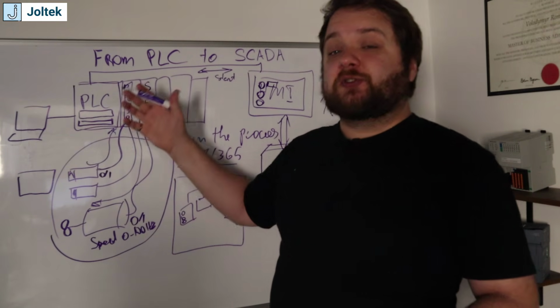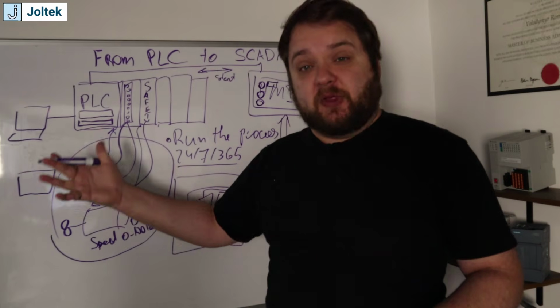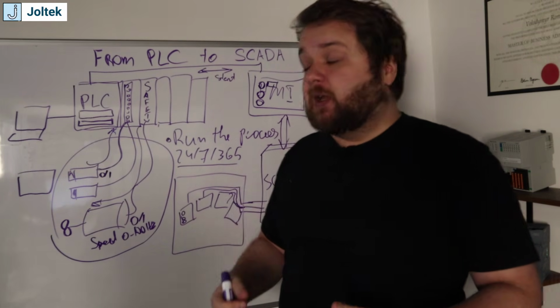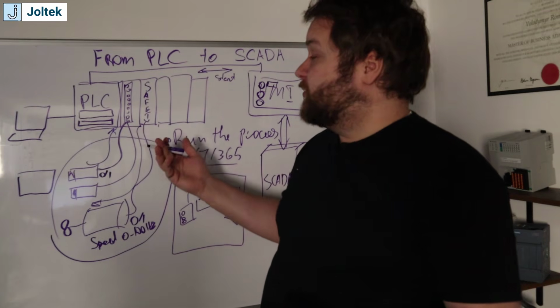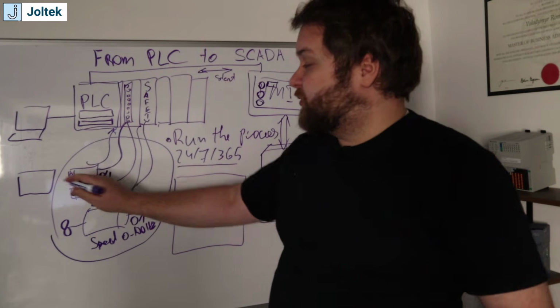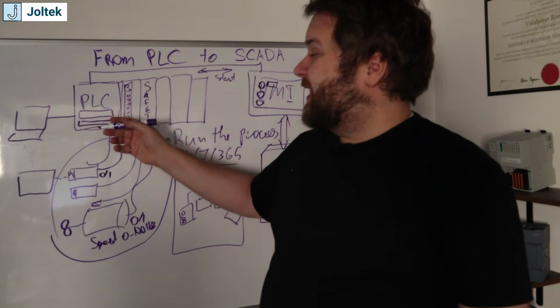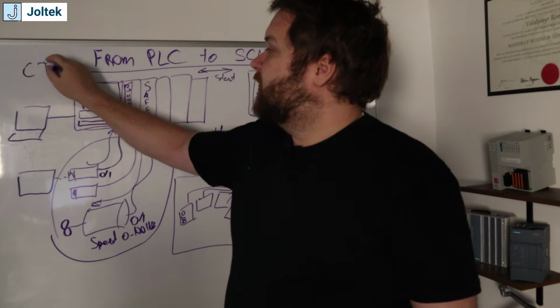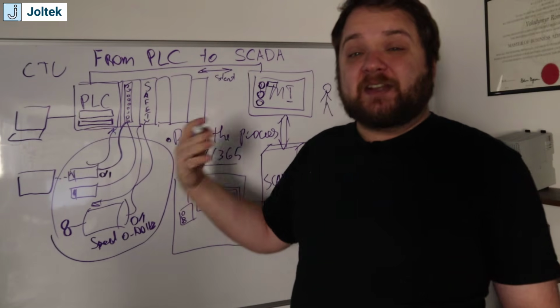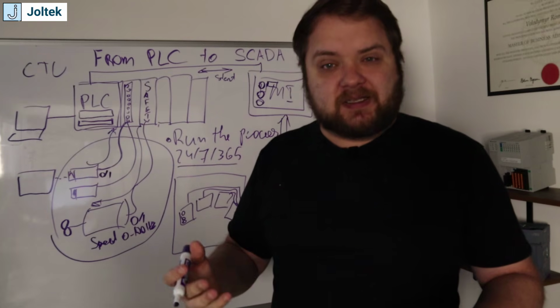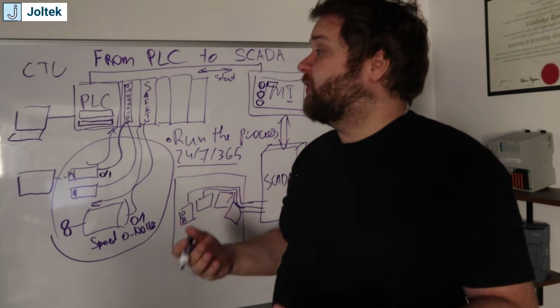Your PLC is going to be a lot more capable than that. And if you have done any amount of PLC programming, you will know exactly what I'm referring to. And let's take a simple example. So if we have a box present sensor, well, we can create a counter, right? So CTU, count up, that will increment based on how many boxes we have seen in the last hour, in the last shift, maybe in the last week.